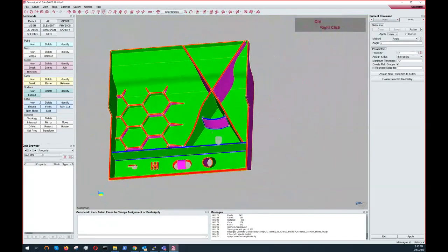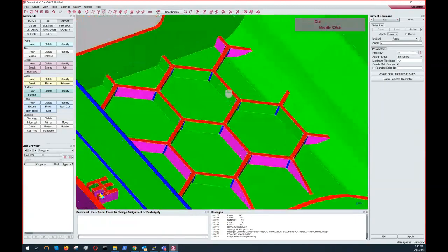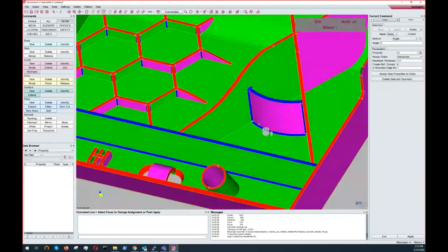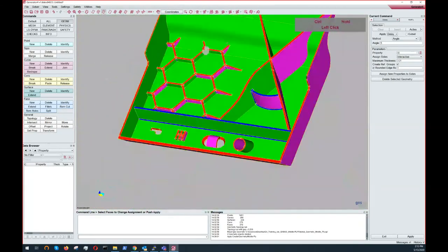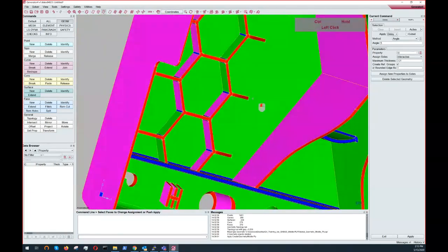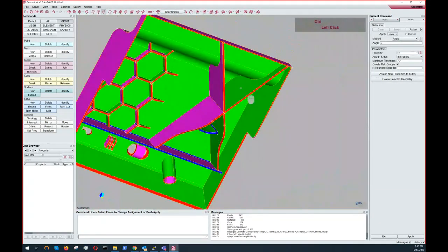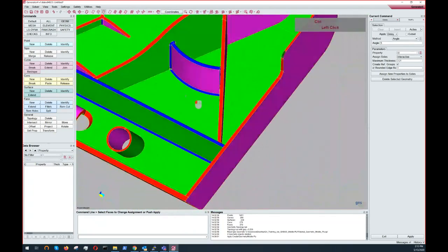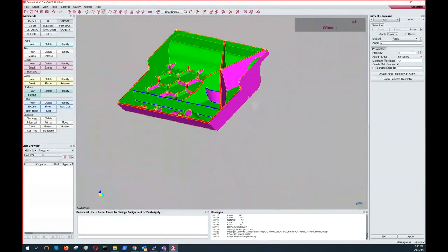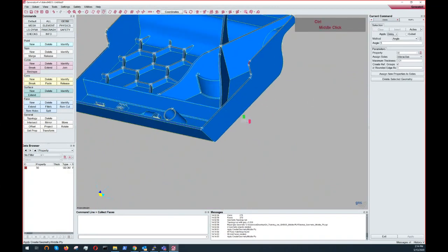So it's really worth it to take a little time to check if all the definitions are correctly taken, because it will reflect on the results. So it's good to give it some time to check the model. This one looks really good now. So one side is rose, pink, the other side is green, and the edges are all marked red, except for the rounded ones that are used for the definition. So with right mouse, I can confirm this command, and then generator creates the middle surface.